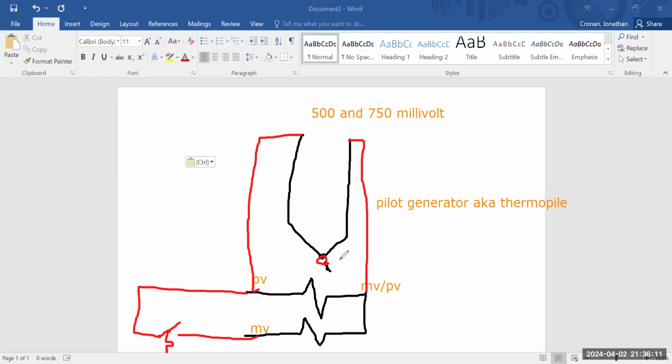So like the apartments that I've lived in that had a standing pilot on the wall furnace, that thing's putting off heat all summer. It's 1,000 BTUs per hour. It's not a lot, but it's definitely putting off some heat. So any apartment I've lived in that had a standing pilot on the wall furnace, I'm going to kill the gas come summertime, come spring. I'm shutting off the gas. And then in the fall, I'm going to go ahead and relight that pilot.